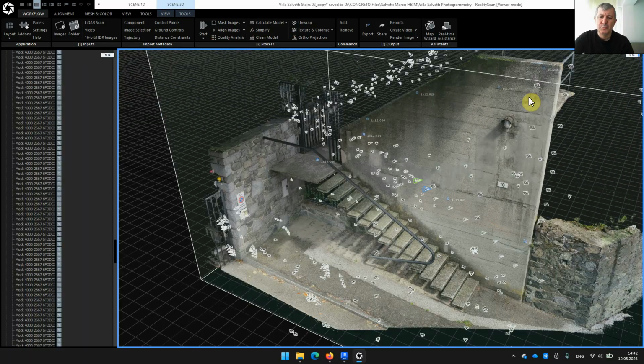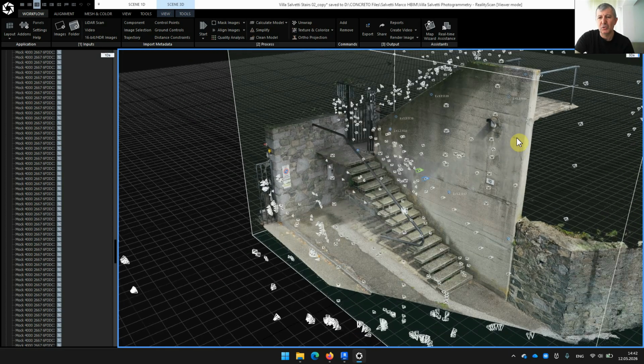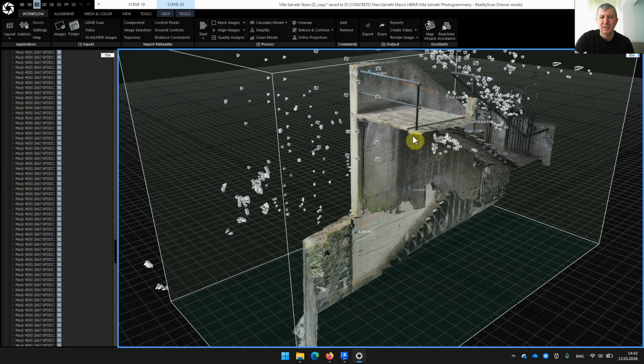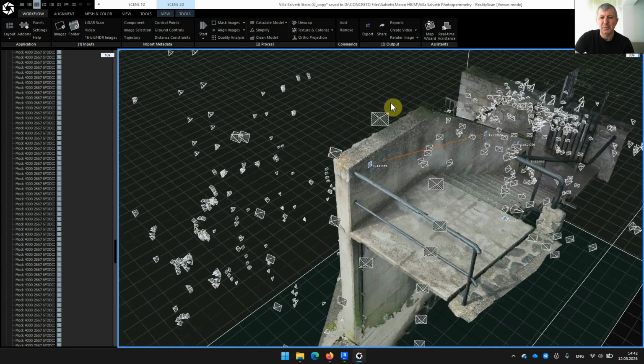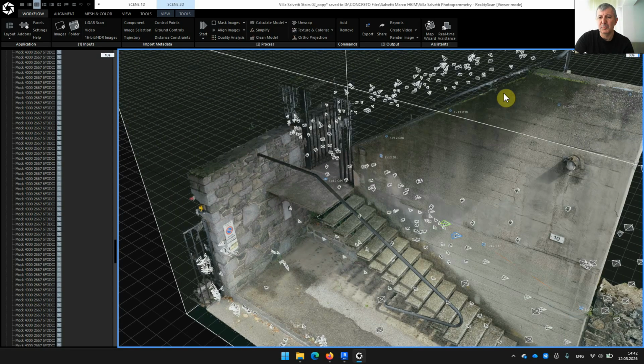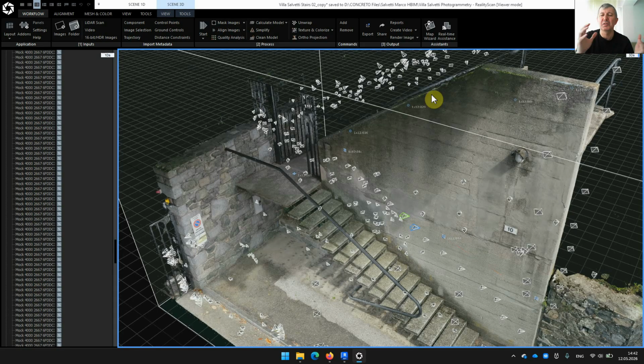You capture the existing situation, for which you could use 3D laser scan, which you experienced last summer. You can also use digital photogrammetry, done either terrestrially, with a camera on the ground yourself, or with a drone that you fly and take photos.